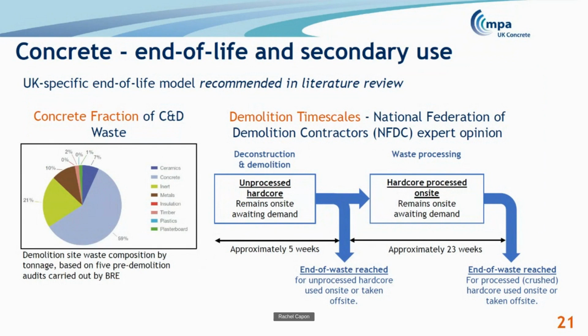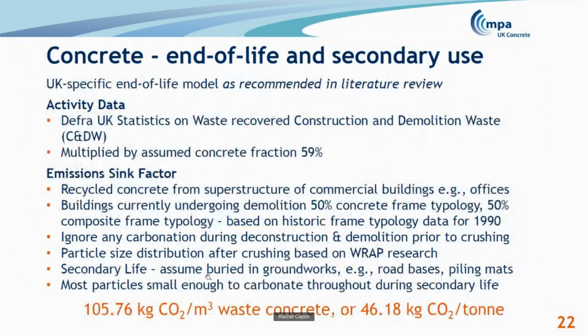Moving very quickly on to the end of life and secondary use of concrete. The literature recommended that we develop a UK specific end of life model. We've looked at demolition timescales, getting some input from the National Federation of Demolition Contractors. There is a limited evidence base for how much of construction and demolition waste is concrete, but we've taken this value of 59% from work done by RAP and BRE. And our activity data comes from DEFRA statistics on waste recovered, and specifically construction and demolition waste recovered.